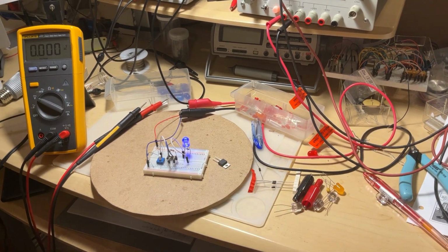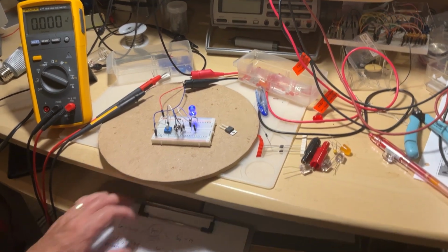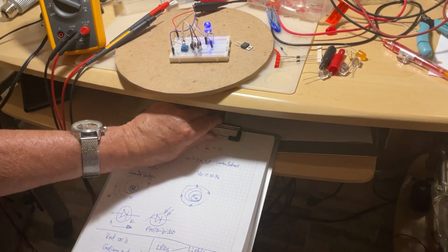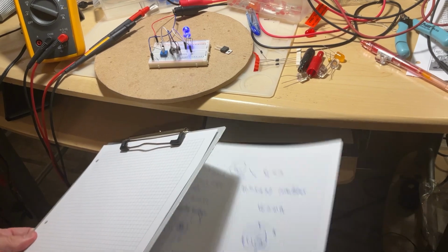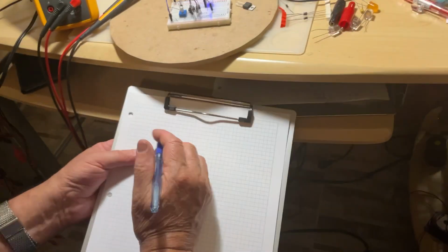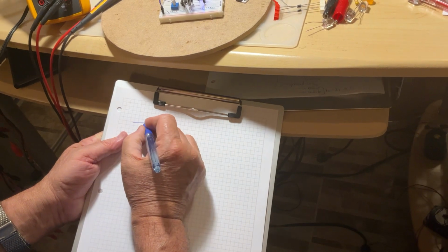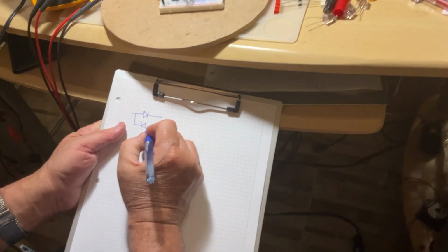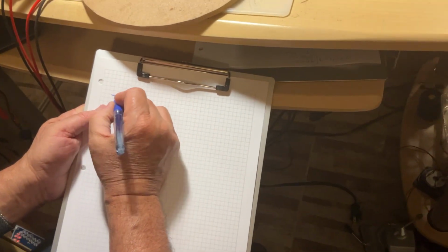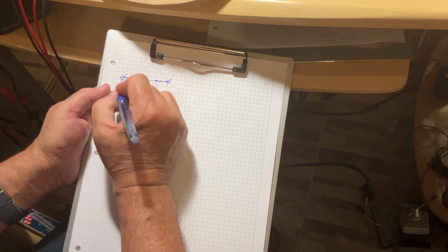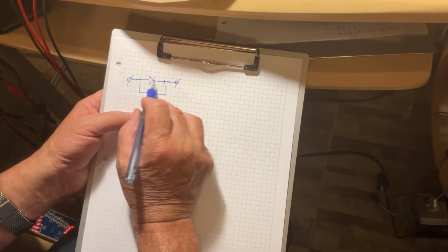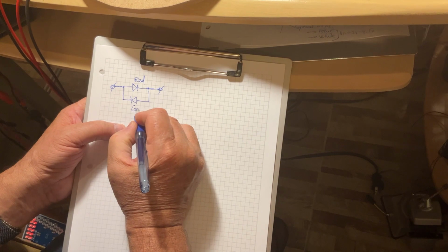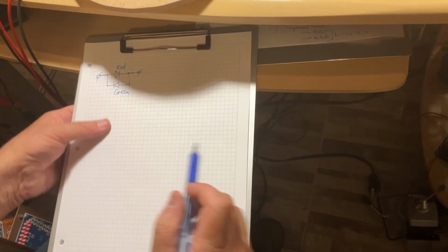And there are also some very special diodes. Let's say they have an arrangement where they have one diode like this, in parallel with another diode connected the opposite way, and out of that assembly, they have 2 terminals. If you energize this one the forward way, you have a red. If you energize this one the opposite way, you have a green. Let's take a look.